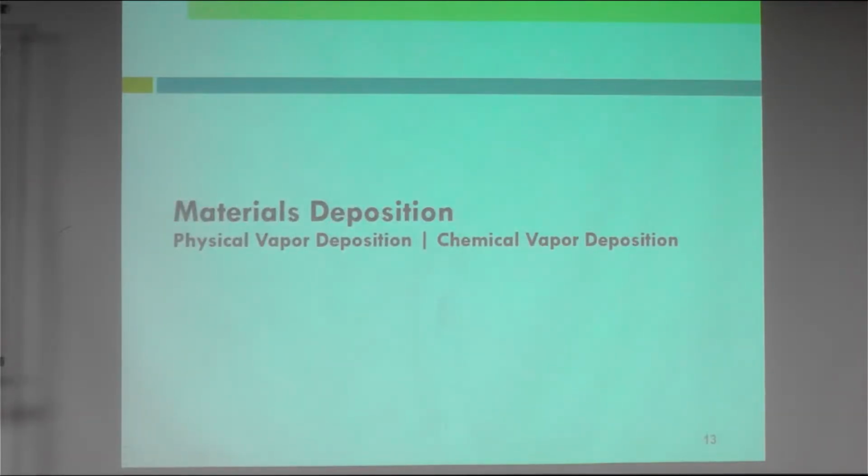So next, we will look into the next material deposition, which are physical vapor deposition and chemical vapor deposition. These two you might use for the deposition of metal, and for organic and inorganic materials as well, such as silicon dioxide, but with different intention. I mean, in comparison with silicon dioxide growth using a thermal process.